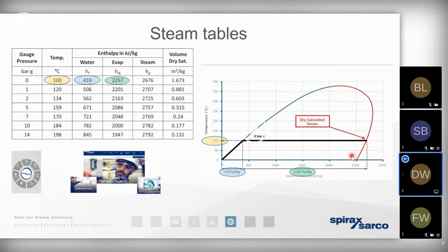And as we mentioned last week, wet steam, if there's a significant amount of moisture entrained within the steam, it's more likely to condense out. It's more likely to give up its heat energy to the distribution pipework than it is at the process.